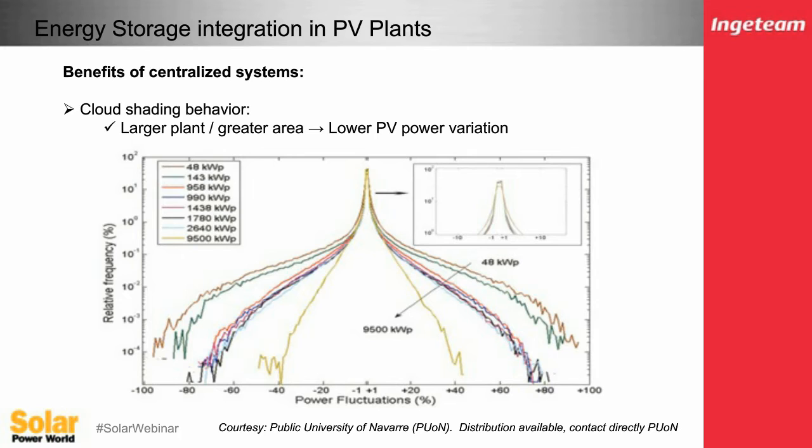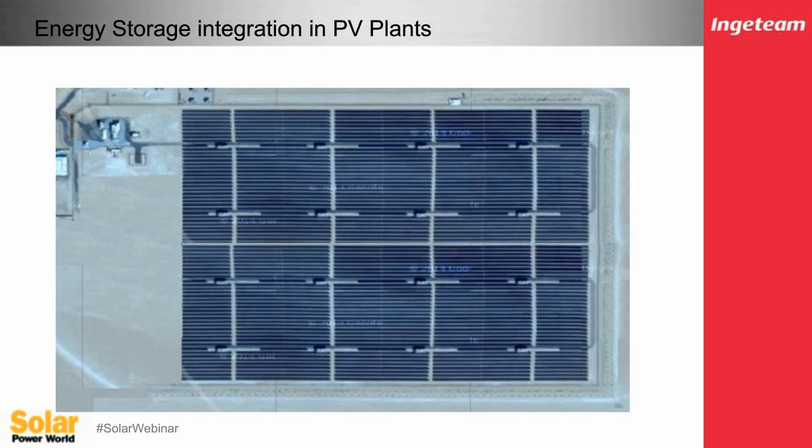And when you take this into account, a key takeaway, especially when you're considering a ramp rate control scheme, is that there's less demand in the sizing of batteries to take into account that variation in power, which you have a demand for when you want that control scheme for the grid operator. So let me paint a picture for you here.